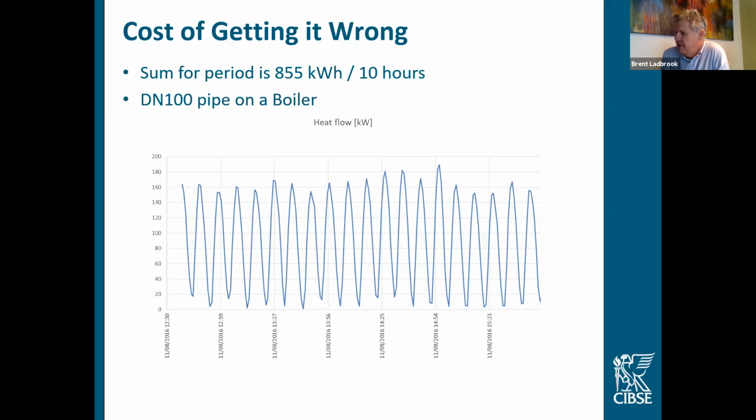Typically, that's not done for thermal meters. There's nothing to stop you, but your cost of installation goes up quite a bit. I would see that more in a plant room type situation rather than a sub-meter out in the field on a level of the building. Typically for thermal meters, that's not done. But you could do that, nothing to stop you, but your mechanical costs are going to go up a lot higher than not doing that.